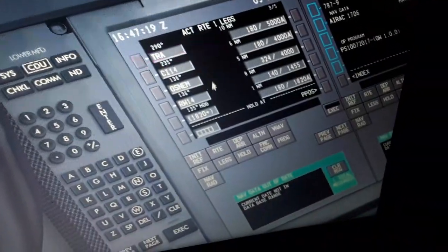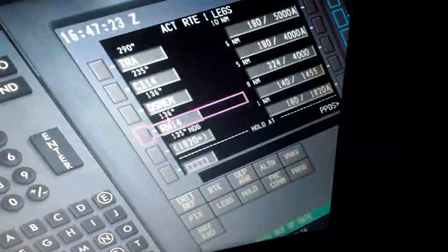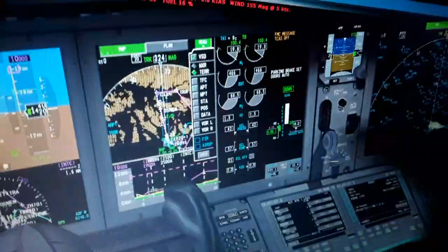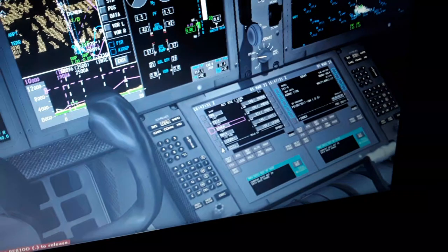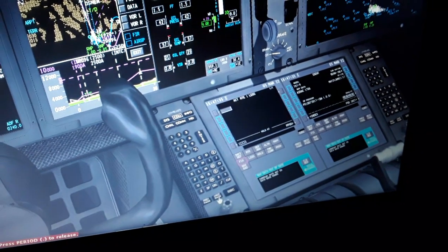Then we have the terminal approach, the STARs, the terminal arrival waypoints and fixes here in the flight management computer. Runway 14, 140 knots, the airspeed at touchdown, and the barometric altitude. So you can see all these waypoints we have to traverse through. They're depicted here also.